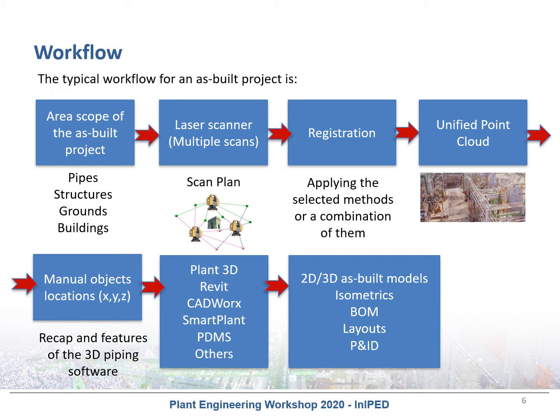The second issue you have to think about is the methodology you will use for the registration of the multiple scans to obtain the unified point cloud. The methodology will condition the scan locations. The third item you have to think about is how you will divide the scope area into small parts. Surely you will need more than one unified point cloud. That's why it's important to create a structured unified point cloud.